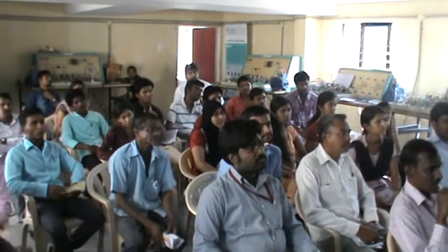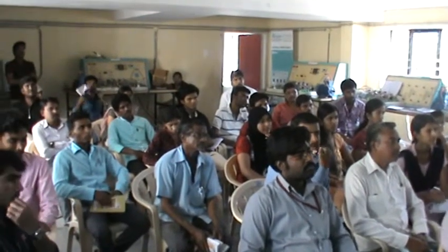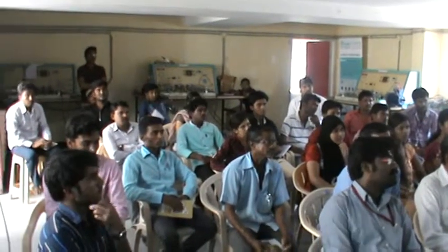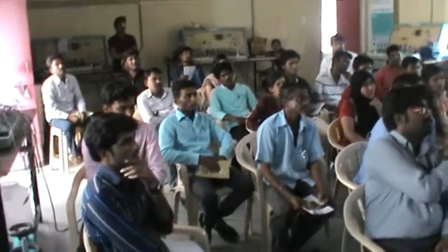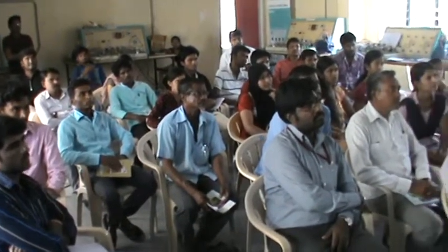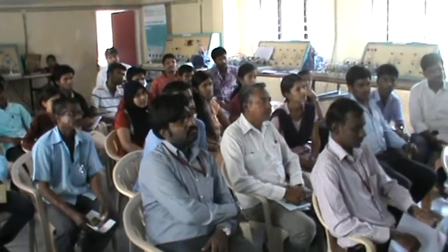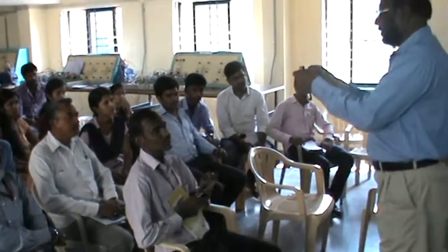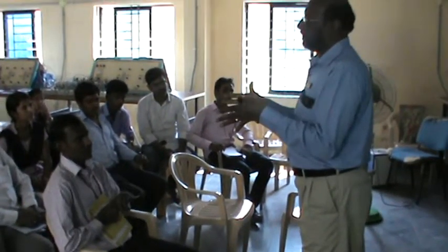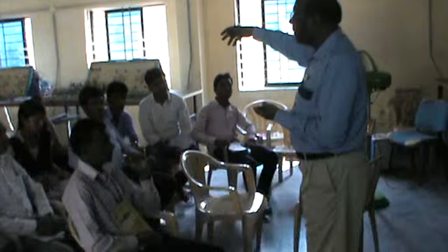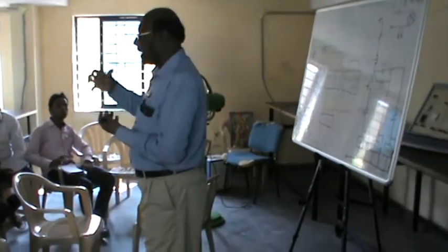So any problem, definitely you already understood. In that, our Mr. Shivsharnappa asked, sir, how to select any contactor, let it be Siemens, let it be L&T, whatever it may be. First you have to check which is the power contact, that you know how to check. Afterwards NO, NC, then coil. And in some cases you require some more NO. You can add an add-on block. You have seen the add-on blocks. So any number of NO, NC you can add.